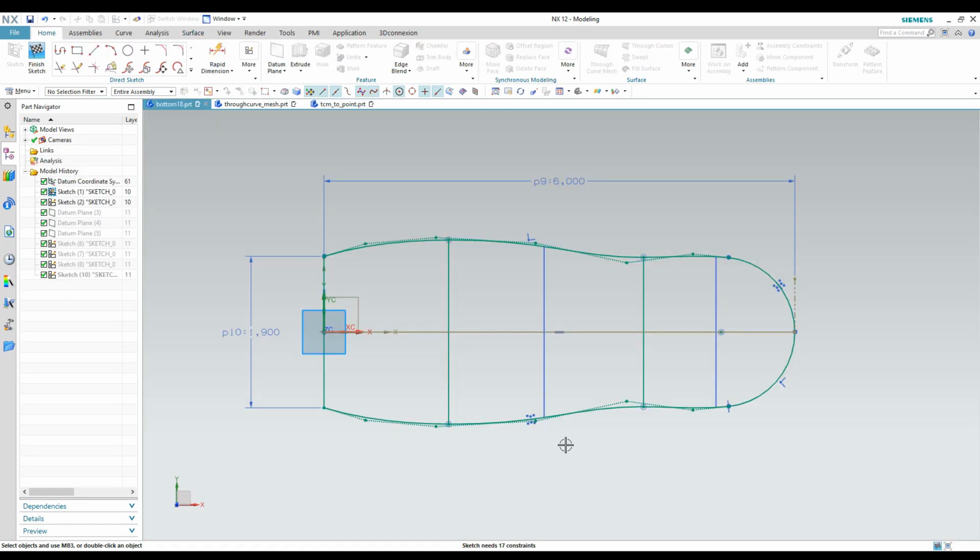All right, so let's move on now and talk about the part that we started with, that remote control housing, and I'll talk to you about how to make the defining strings that you need and how to tie them together so that they do actually intersect each other and you don't have to worry about any problems down the line or your surface just not being able to be created because your strings don't intersect within the tolerance.